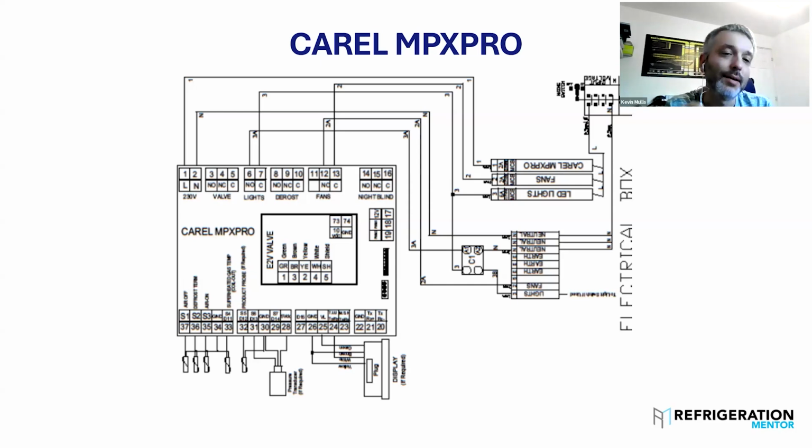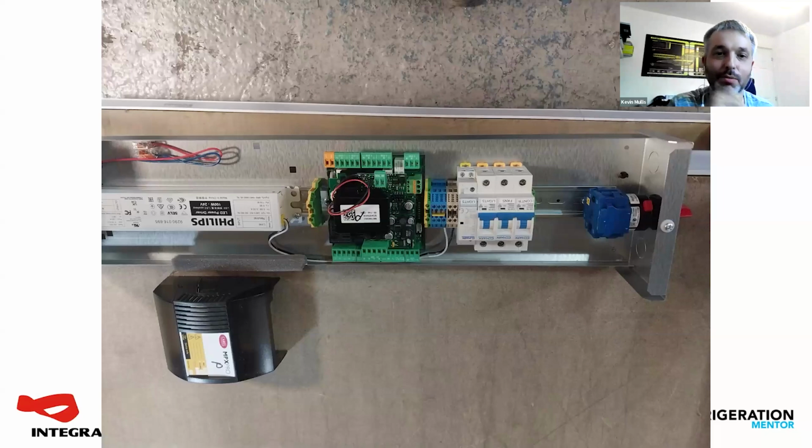The controller will usually be able to tell you on the fault codes that will come up on Carel, it's EFS comes up on the display if it thinks the coil is faulty. It will not tell you if the valve is stuck. All it knows is what it can see electrically. It doesn't know if it's mechanically stuck. We talked about this last time, didn't we, Trevor, on the podcast? You will need to physically check. If the controller says it's at 0 and it's not saying EFS, it's happy the stator's working and it thinks it's shut. Whether or not it is shut is a different matter.